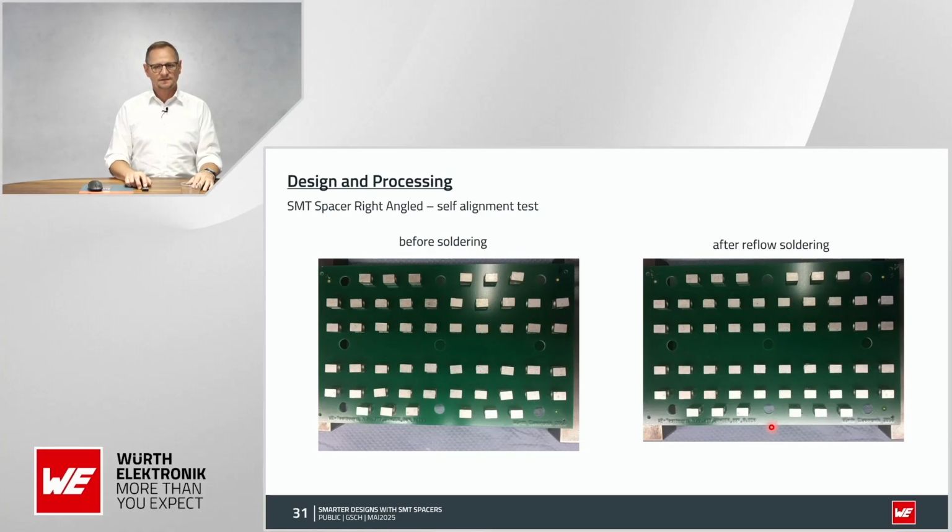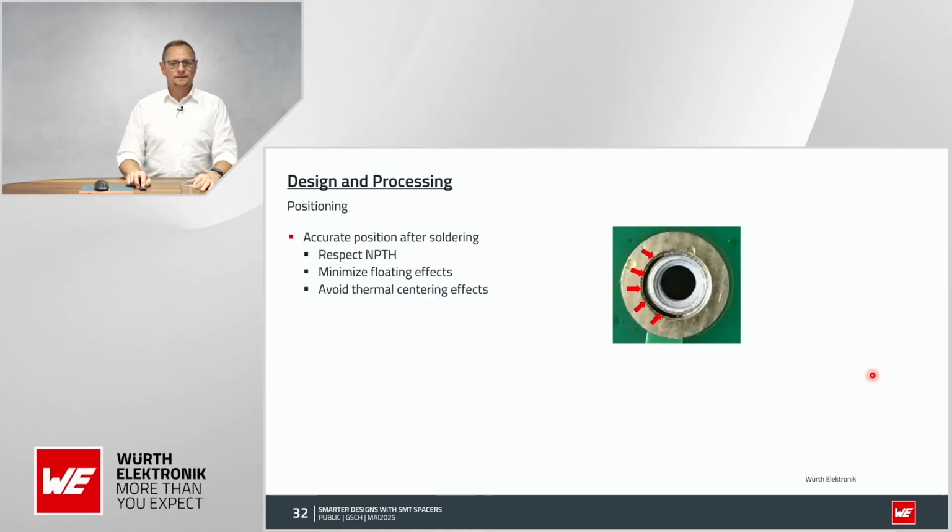So here we have an example. On the left-hand side, we placed some of the right angle types, they did not sit very accurate on its position, and this was after soldering. So by the capillary effects, they drew themselves in the right centered position. I also have a nice video about this, if you're interested. So positioning, it's important to have an accurate positioning after soldering.